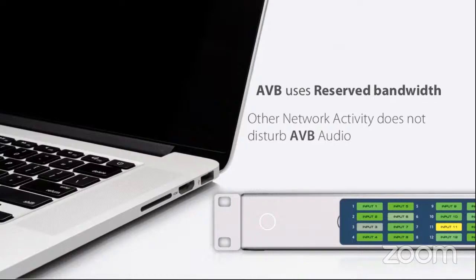And this is where AVB becomes a big advantage over Dante, because it allows you to run your AV network on the computer network that's already doing other things, and the two shall not hurt each other. So there just might be a situation where you cannot run an entirely separate network for your AV side. You have to utilize the existing infrastructure. So if you're in situations like that, AVB might be the route for you to take.